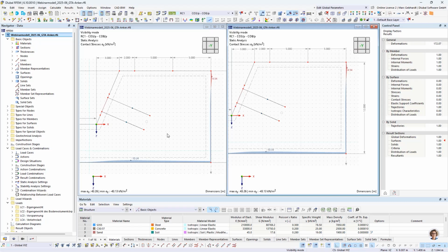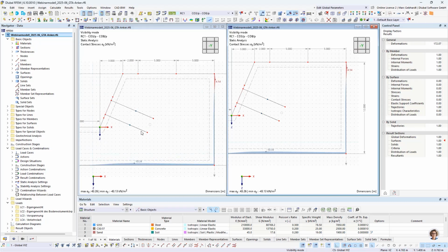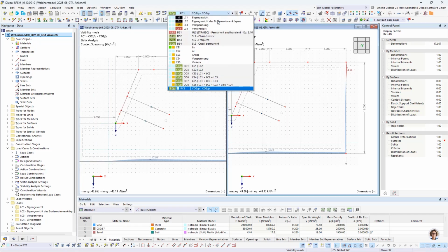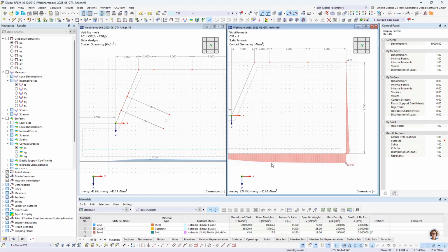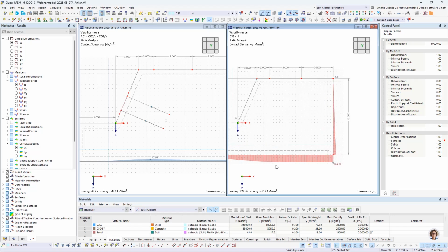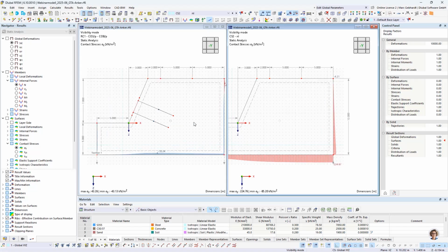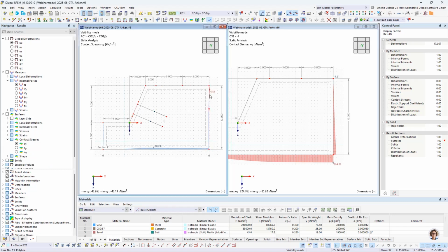And here we see the additional stresses from vehicle load, and here we want to check the self-weight of the soil. And see, there we can show each result, but as you see, it's much less than 10% on the bottom. We only have a higher point on the upper right.